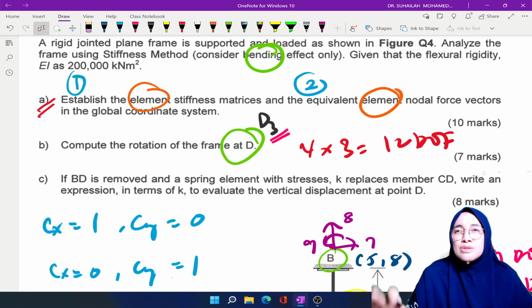By solving simultaneous equations corresponding to the unconstrained degree of freedom system, we will get the unknown displacements. And if we need to continue to calculate the reaction at the support, we will of course continue using the stiffness equation, focus on the position, determine the value based on the position, and calculate the value using matrix multiplication.